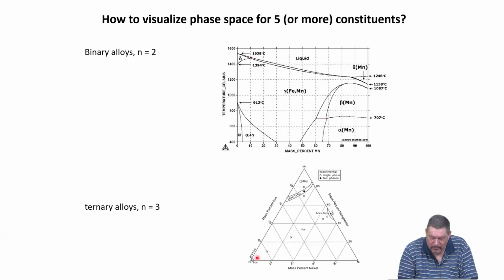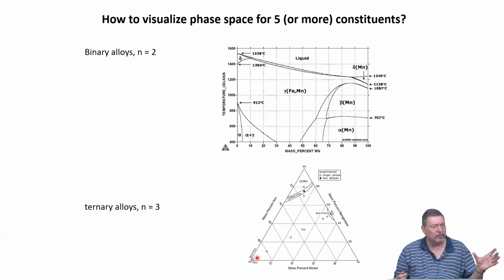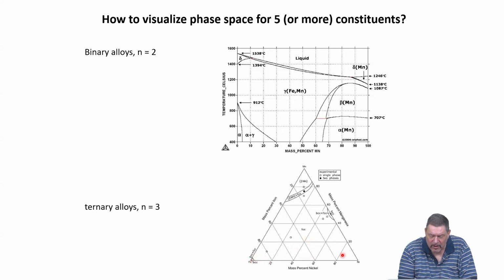And you see that normally what we do, because we don't want to carry prisms around, is that we do isothermal sections. So we have a fixed temperature, and then in the Gibbs triangle, giving all compositions possible in the ternary phase space, the phases present at this temperature in these compositional ranges are given and listed.